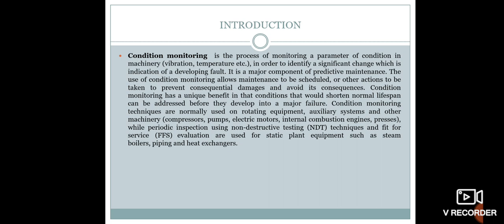Condition monitoring techniques are normally used on rotating equipment, auxiliary systems and other machinery such as compressors, pumps, electric motors, internal combustion engines, presses, while periodic inspection using non-destructive testing techniques and fit for service evaluation are used for static plant equipment such as steam boilers, piping and heat exchangers.